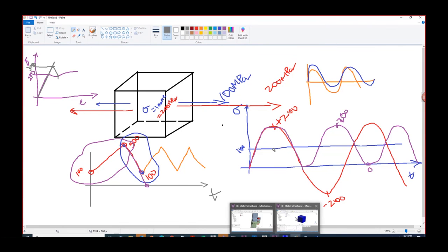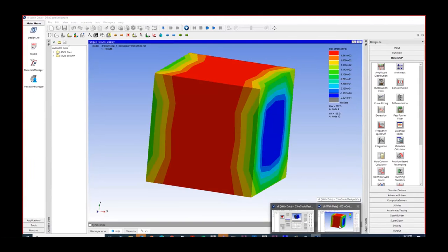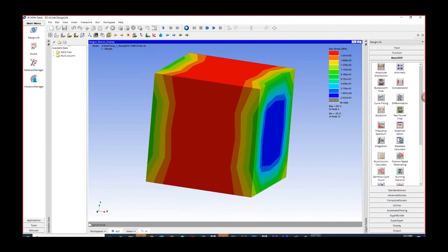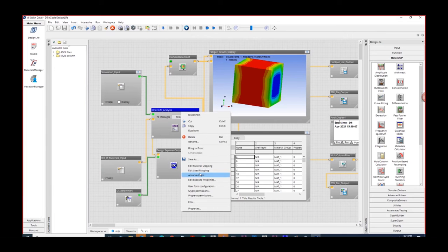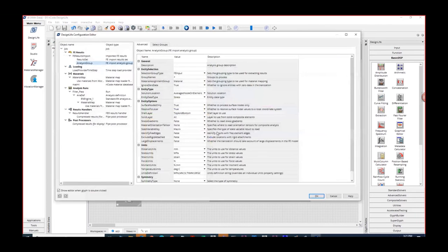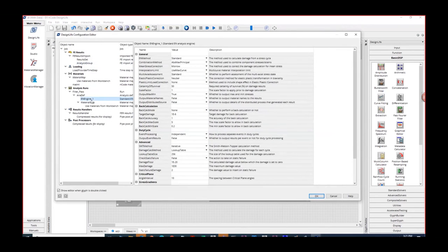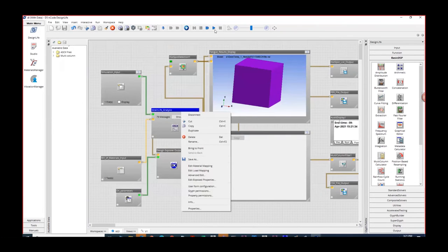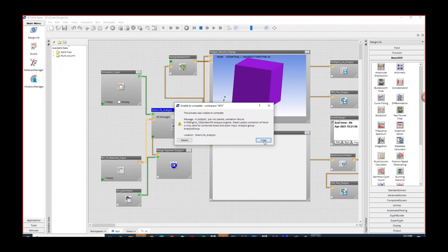We can have two different types of correction here. I will show you. Under the EN engine we can do either Neuber plasticity correction or Hoffman-Seeger. For this problem, I will say no plasticity correction. Then I would expect the max stress to be 300, same as the SN analysis.